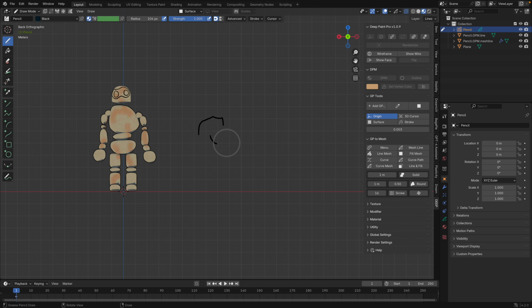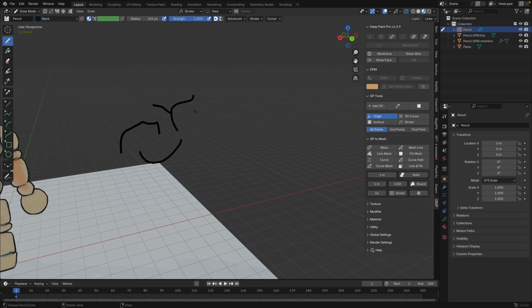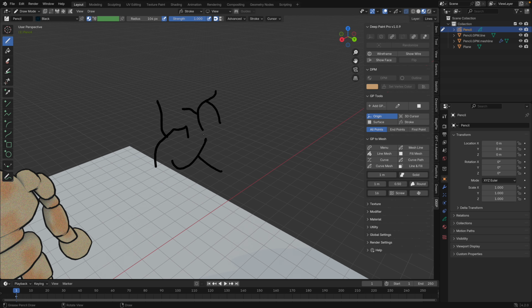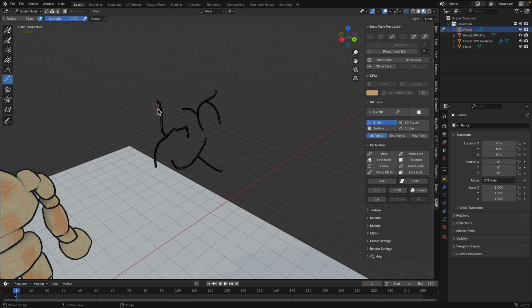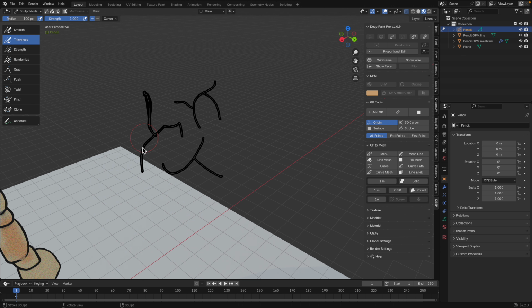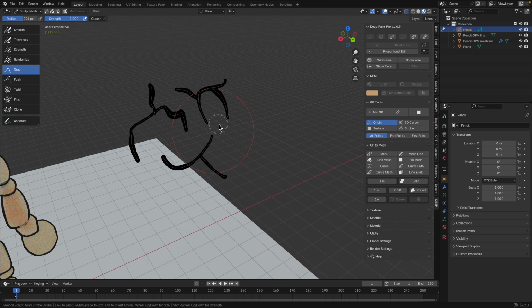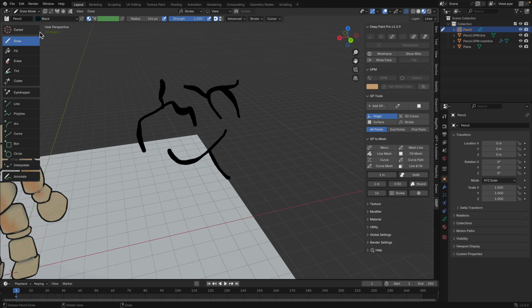If you are drawing with grease pencil, as cool as it is, we can also use the stroke, as we already know. On top of this, of course, we can always use sculpt. And the sculpt, you can adjust thickness. So probably not many people know how powerful this is, like to be able to sculpt the stroke. You can randomize with the grab. I think grab is really powerful because you can sculpt this grease pencil after the fact. So back to draw mode.